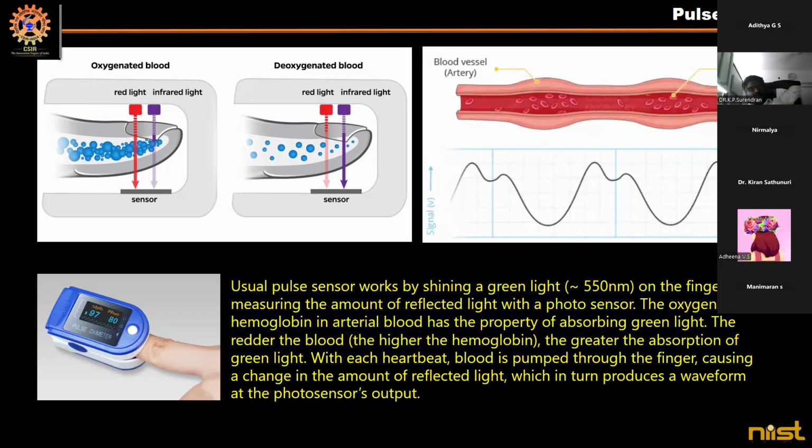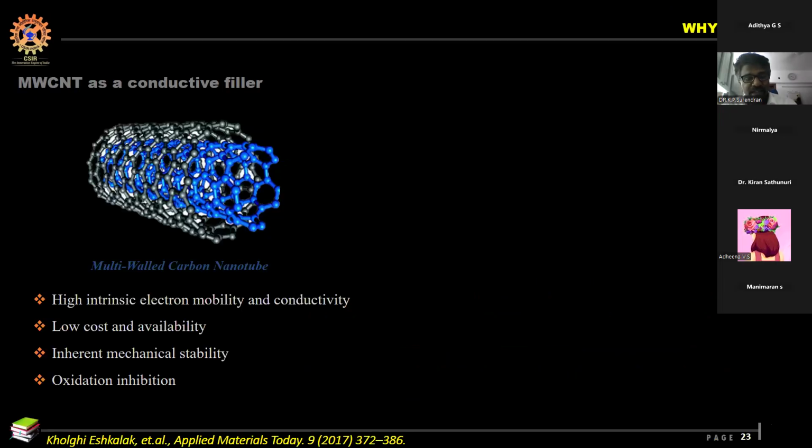We made them using a simple technique called piezoresistance. Piezoresistance means the moment you apply a force on a material, its resistance changes. If you apply a force and its voltage changes, we call it piezoelectric. If the resistance is changing, it is called piezoresistive. These kinds of sensors are very popular in electronics, but they are very difficult to fabricate because their accuracy level is very, very critical. But we have succeeded in making this kind of material.